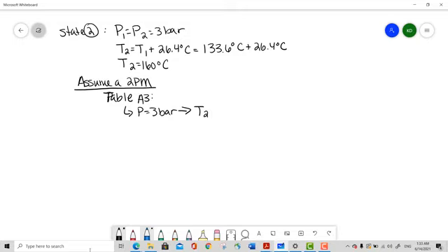Because that's actually what we pulled from the table. So we know right off the bat that our temperature is larger than the Tsat. And then per our flowchart, we will go to superheated vapor tables. Okay, and I'll even put from flowchart.